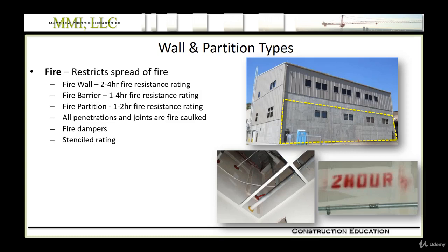So I've noted fire resistance rating in terms of hours a number of times so far. The question comes up, how does someone know the material options or the combinations of materials to achieve a certain rating? Well, code is very specific in identifying methods to determine fire resistance, and it provides means to create your own assembly with backup, design documentation, calculations, and testing using procedures prescribed by ASTM, American Society for Testing Materials, which is now an international standards organization, or UL, Underwriters Laboratory.